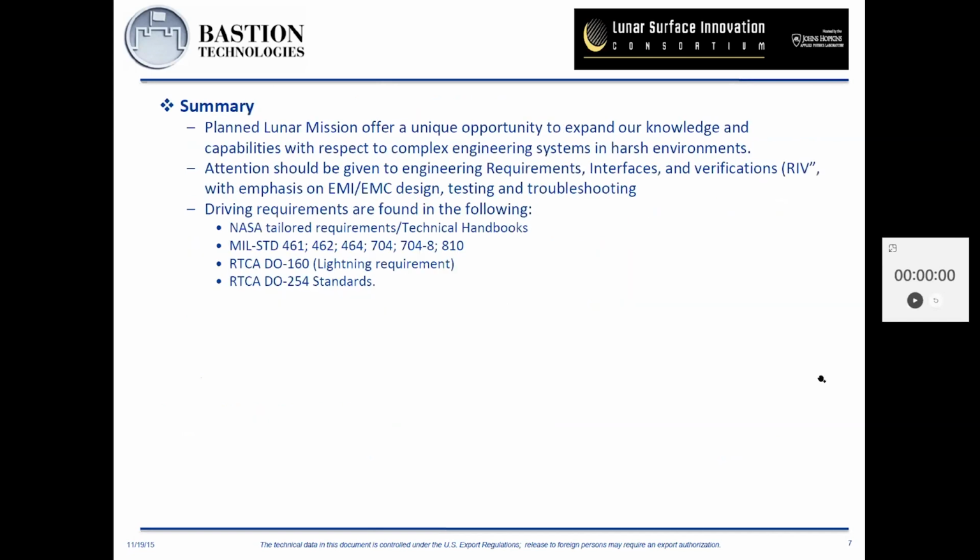So, the summary. Planned lunar missions offer a unique opportunity to expand our knowledge and capabilities with respect to complex engineering systems in harsh environments. Attention should be given to engineering requirements, interfaces, and verification, as called out by RIV, with emphasis on EMI/EMC design, testing, and troubleshooting. The driver requirements are found in the following: NASA tailored requirements, technical handbooks, military standards, and also RTCA DO-160.